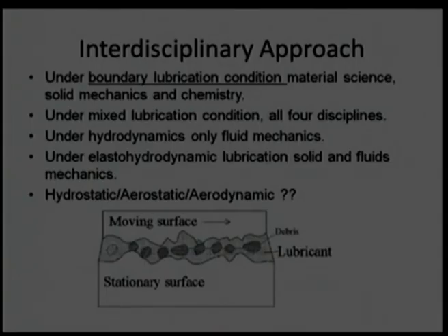If there are some dirt particles passing in the liquid, they can occupy the space between surfaces, and then they can reduce the film thickness, or effectively increase the surface roughness. So, every hydrodynamic mechanism can be shifted to mixed lubrication after operating condition. So, in real sense, we need to account all 4 disciplines whenever we want to attack any tribological problem or any tribology problem.